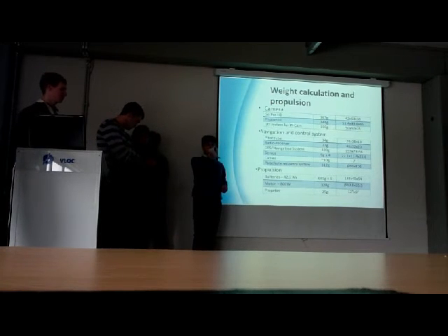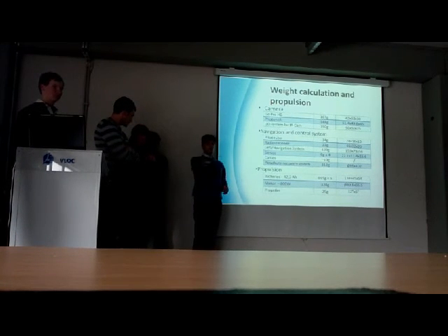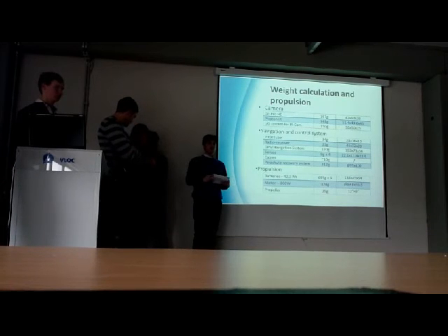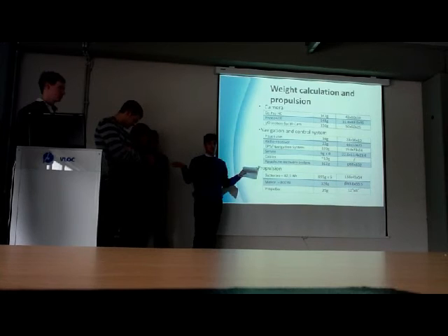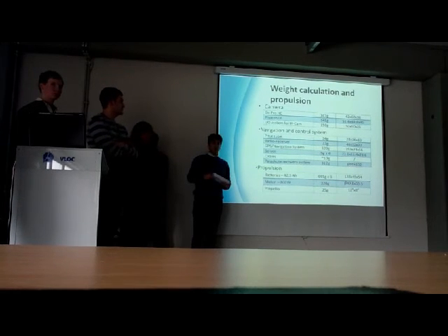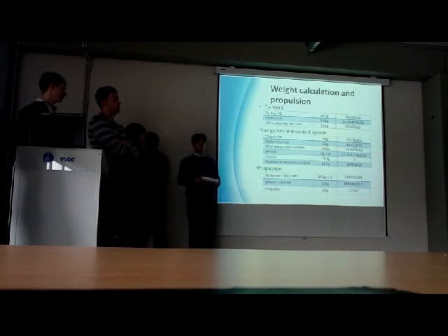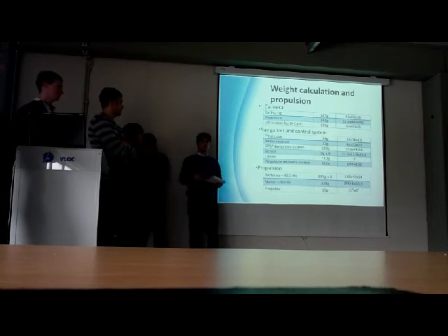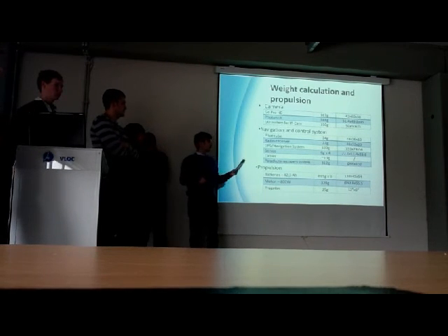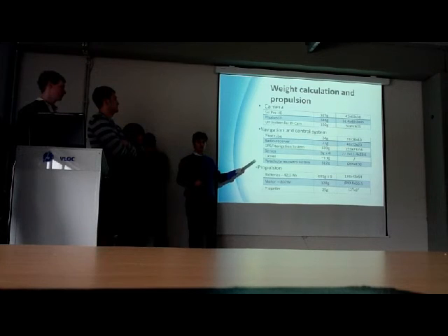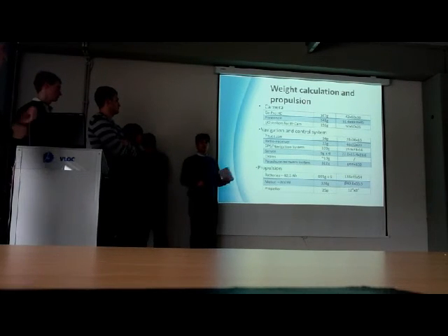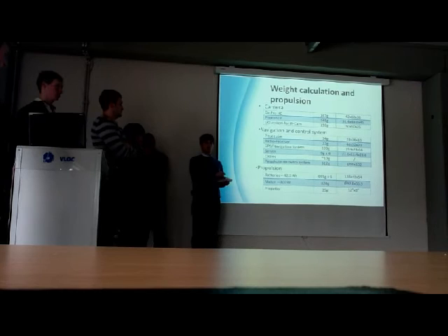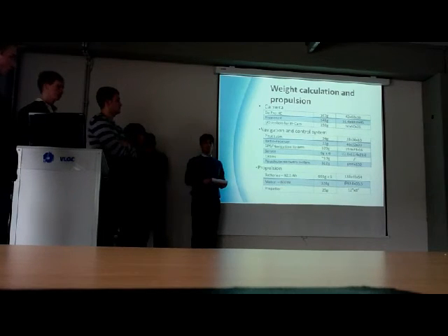We want to be able to move smoothly and with as little weight as possible on the wings. The weight of an electroactive polymer is proportional to the number of wires that we add on the surface. The number of wires depends on the aerodynamical loads on the control surface.